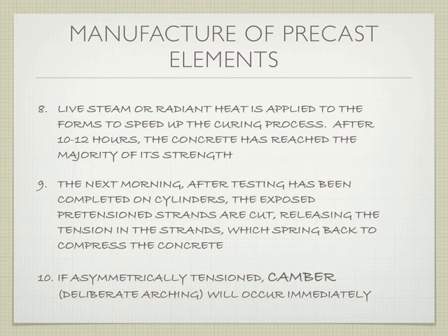So when we relieve the tension in these pieces, and we do this by just cutting through the tendons, the friction of the bond between the concrete and the steel means the tendon shrinks just a little bit, because that tension is released. And when that happens, we immediately get that intentional camber, that little bit of bend, if it was intentional.